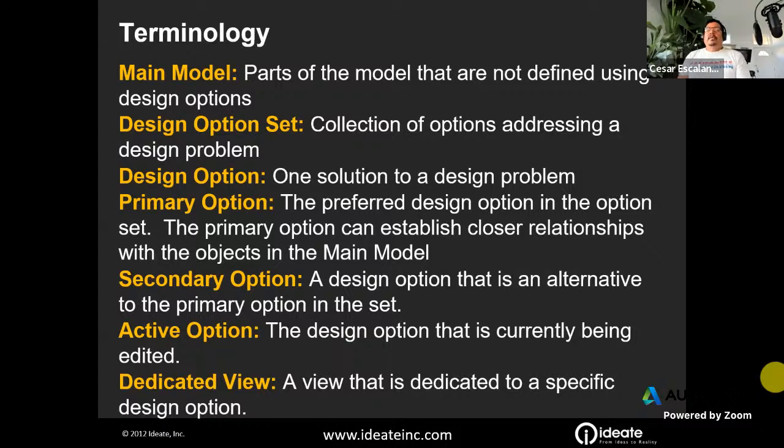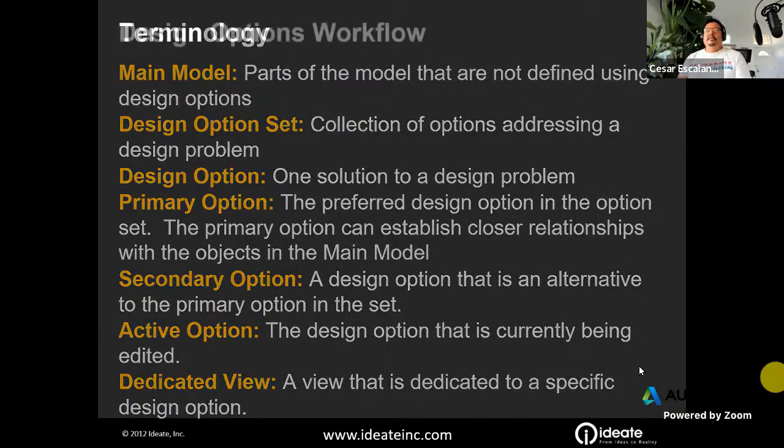And then views can be dedicated to a specific option. In the instance properties of the views, now you have the ability to associate a particular floor plan to a particular design option. And you can do that inside visibility graphic override.